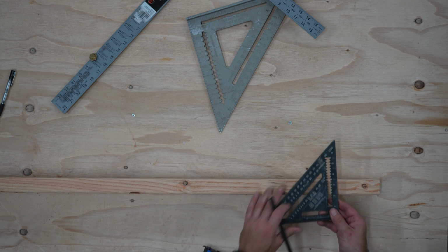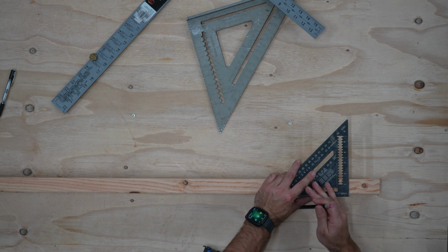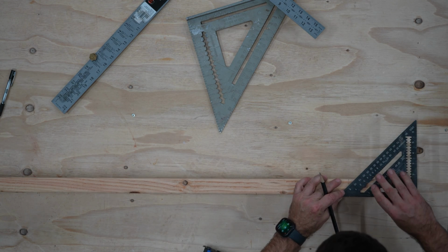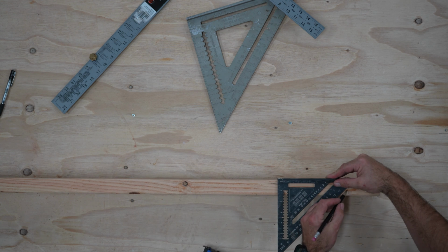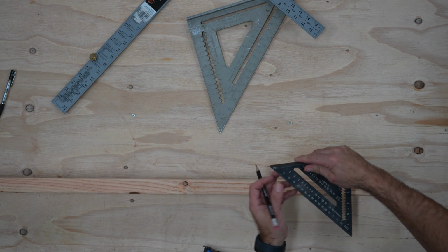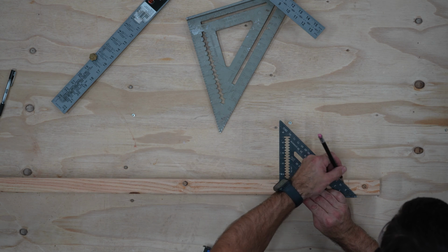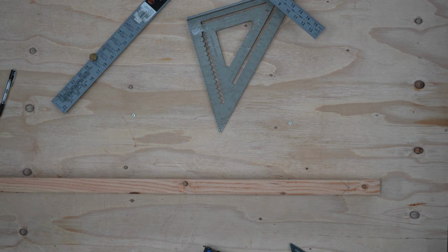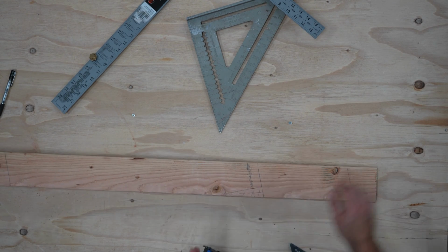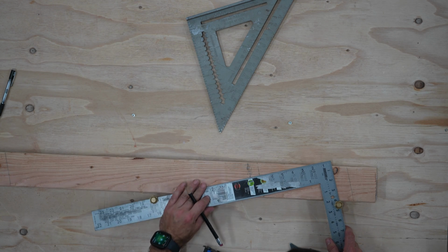Now the start and end plumb cuts that we have made at each end need some more work. These are the farthest points on the rafter, and we need them to be cut to a point. Doing the same to each end, I mark the end of one of the marks across the edge of the rafter and find the center point, which is 3/4 of an inch along that line. Then I make a couple of 45-degree marks from the edge of the board to that center mark on each side. This is an easy spot to make a mistake and draw the 45-degree marks in the wrong direction, so I need to make sure that the point points towards the ends of the board. Then I need to mark the new ends on both sides with a plumb line.